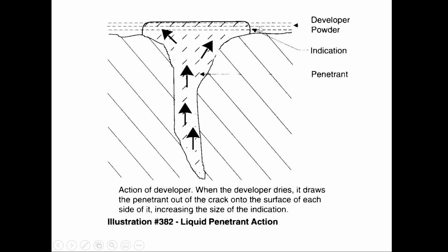So the dye lays down and gets inside these cracks. The dye is also known as a penetrant. And the penetrant will actually go in, and it's not unlike WD-40. It will go inside and find all these little cracks and crevices. It'll eat through and dilute any moisture or oil to get down where it needs to go.